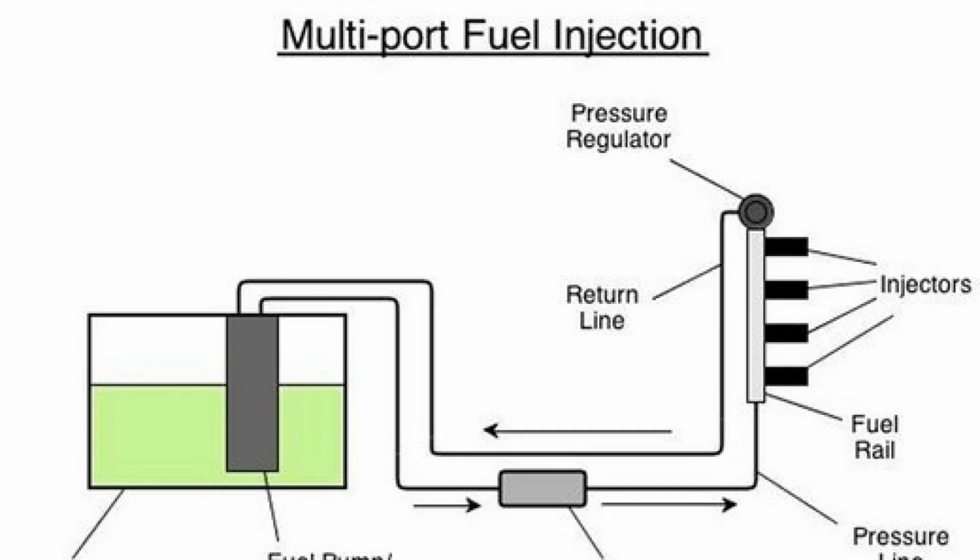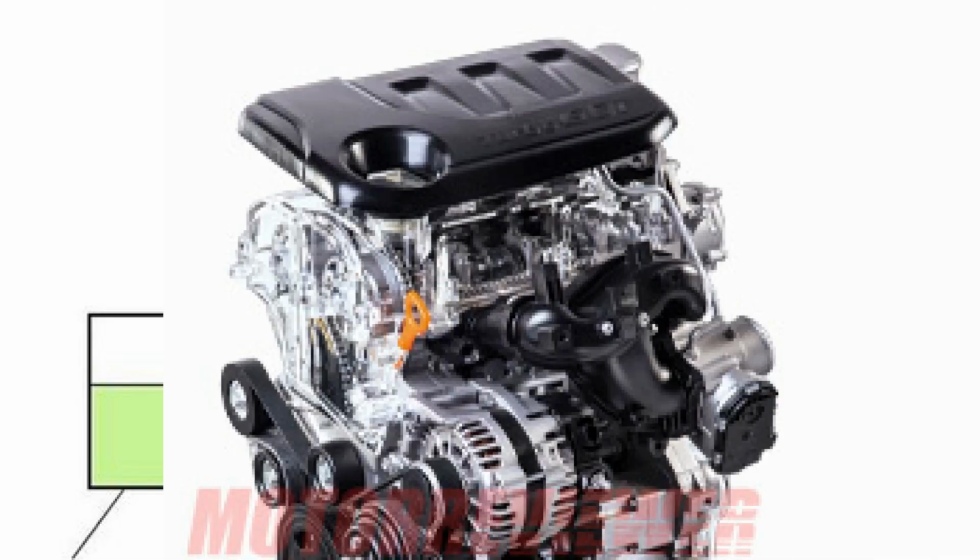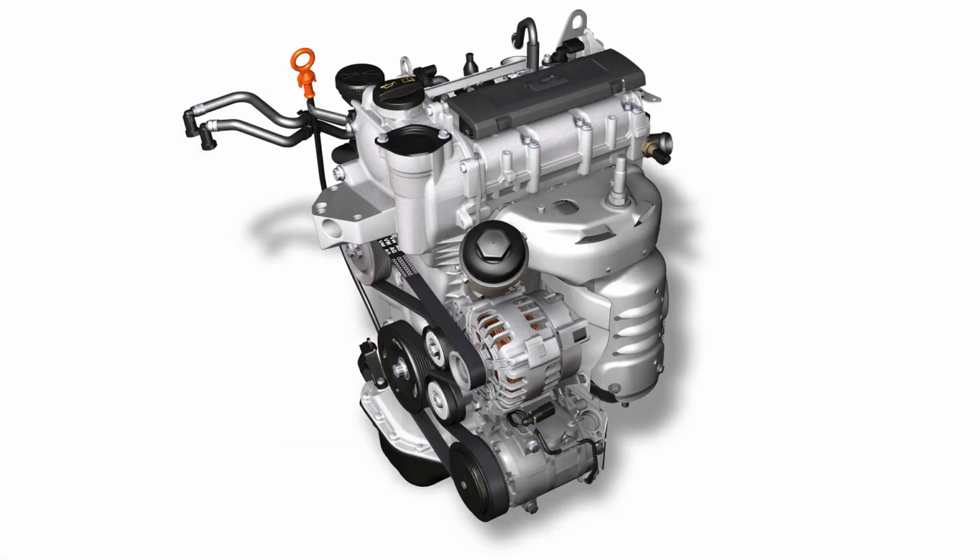The main feature of the design of multipoint injection on the valves is the fuel delivery system. Reading information about the engine speed, coolant temperature, desired and actual load, and vehicle speed allows the ECU, the engine control unit, to accurately calculate the injection time and the amount of gasoline supplied. As a result, MPI engines deliver acceptable torque and peak power with moderate fuel consumption.